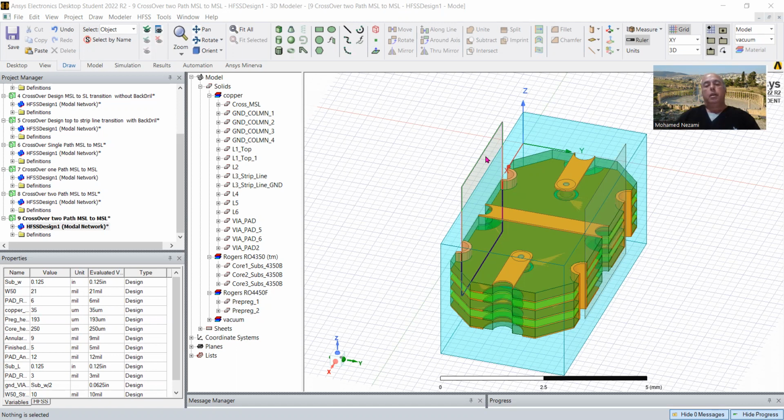So we've got cases where we have multi-layer boards where we need to somehow get the signals through. There's a point where the signals come in and they have to jump over each other to continue. So to make this happen, we have to design a crossover. Crossover meaning two signals, or even one signal that comes in, has to somehow avoid touching another line.